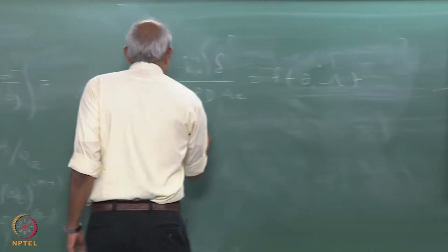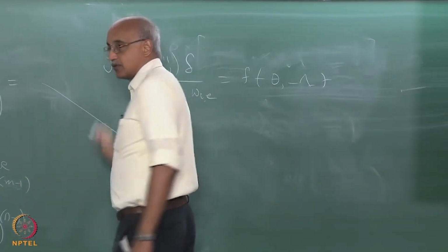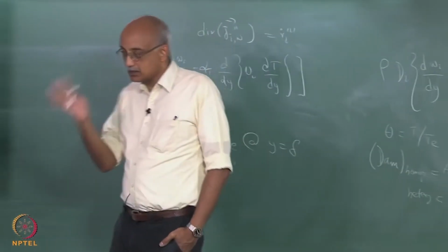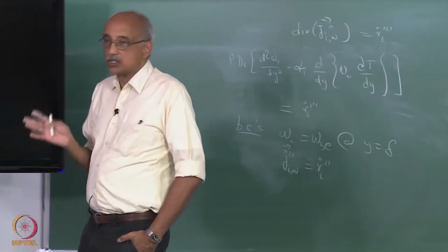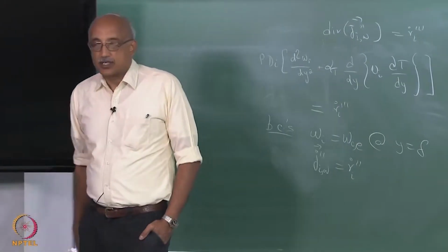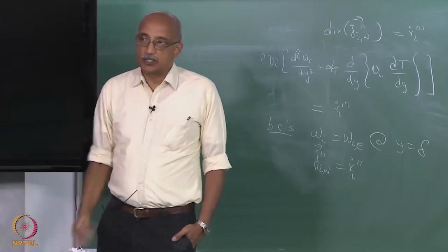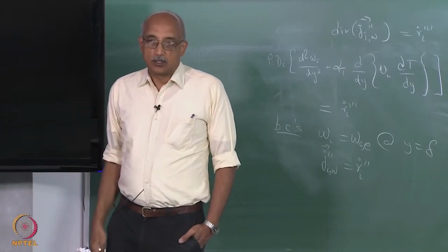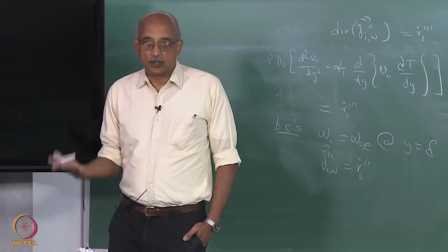So, how do you estimate the temperature at which the transition from region 1 to region 2 happens? Is there a simple way where you can say that this is the temperature at which you transition from being heterogeneous kinetics control to being diffusion control? What would that depend on? It should be based upon the Damköhler number, right?